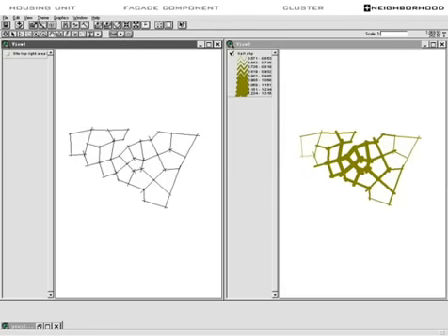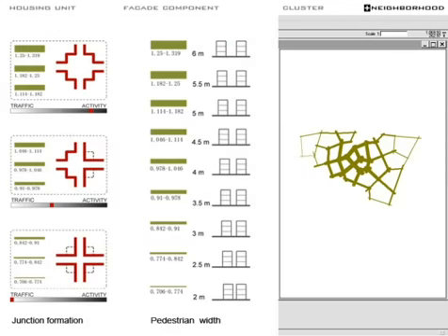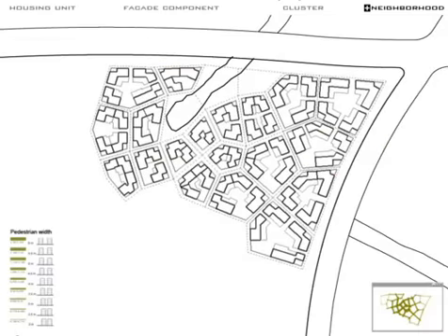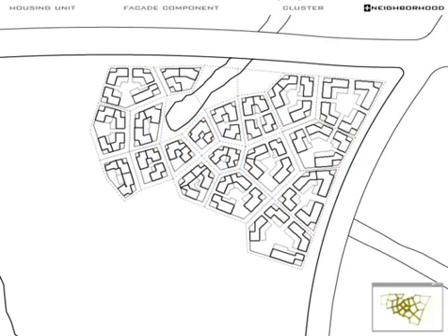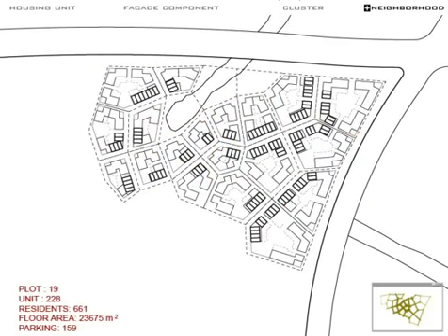Integration, which is used to estimate the frequency of use, mainly the pedestrian flow, has been calculated. Therefore, the width of the pedestrian path and the formation of the junction is determined. Parking is calculated at 0.6 to 1 car per family according to the plot size and housing standard, located on the ground floor. To minimize walking distance, every unit has at least one side for parking, and this formulates the